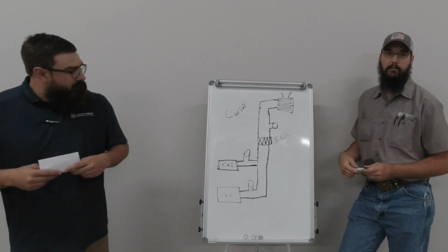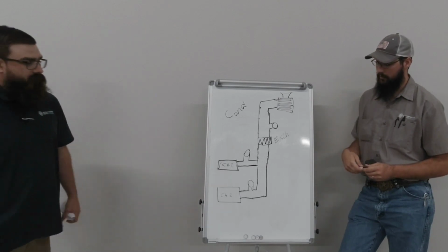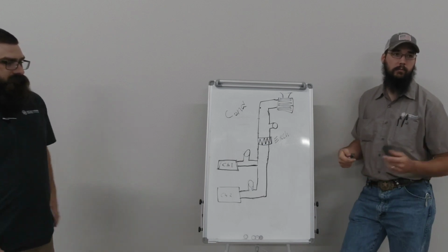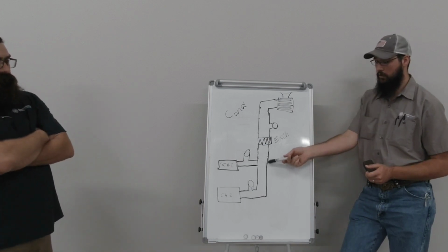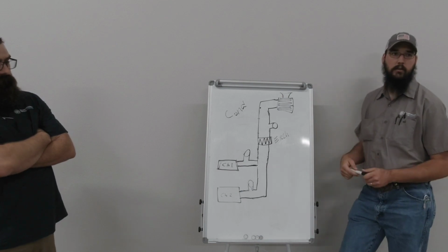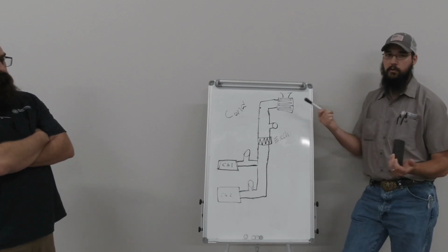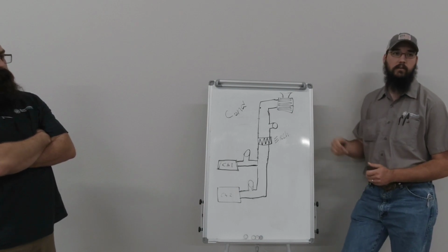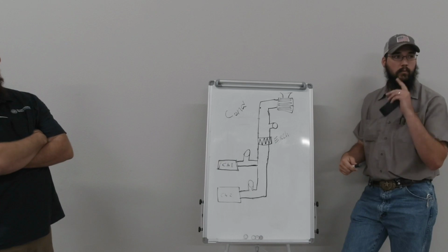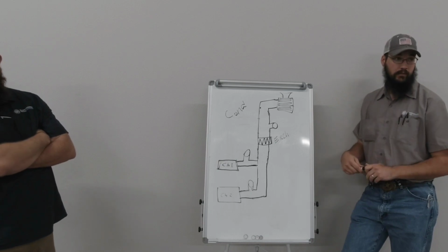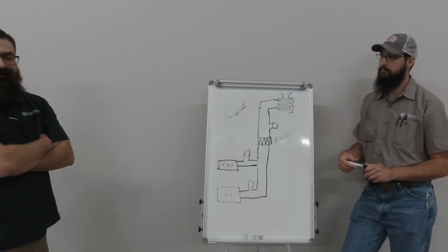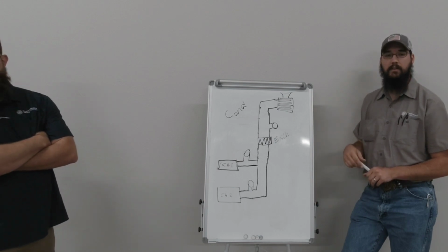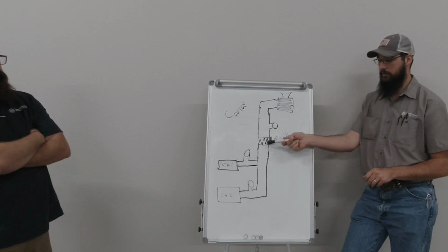So this would be an example of if we had a plated heat exchanger isolating the tower from the equipment. So this would be a closed loop system on a building, and then this tower could be an open loop tower. We see that at Aspen Lake 1. Aspen Lake 1 has this exact setup actually. Also the current setup of Los Angeles too. Not permanently, but current. Oh, that cooling tower they got out there with all that set up? Yeah, and they've got the big blue thing sitting out there. That's what this is. Yep, heat exchanger.